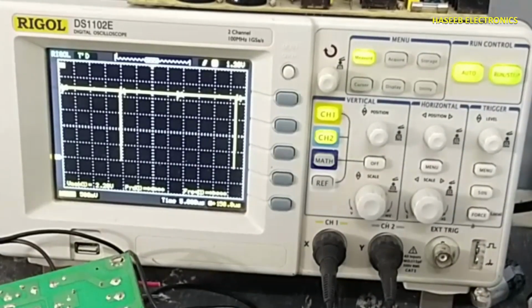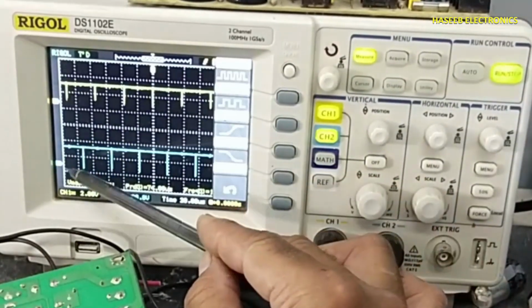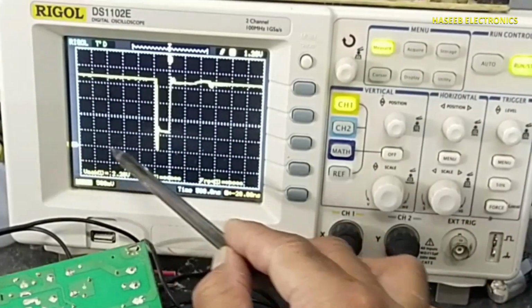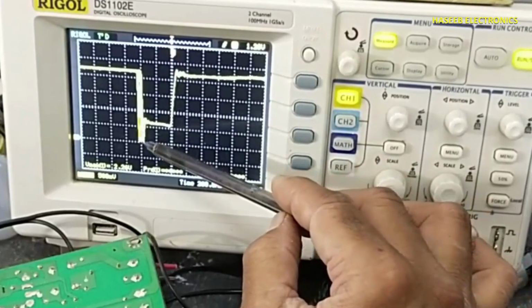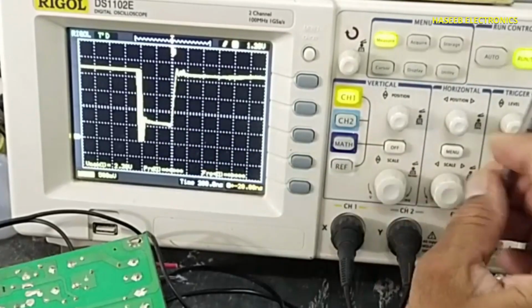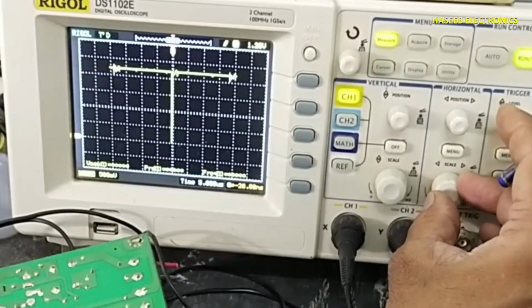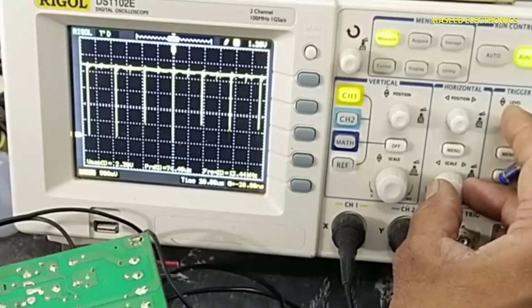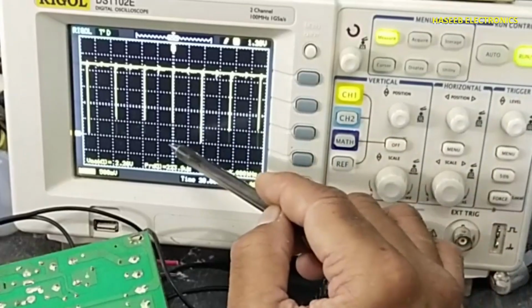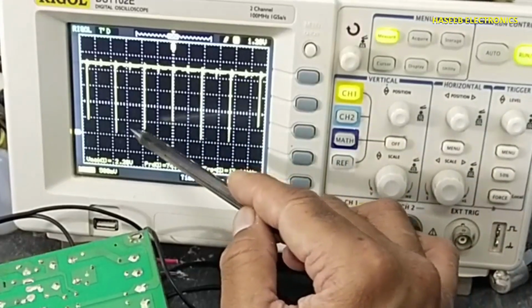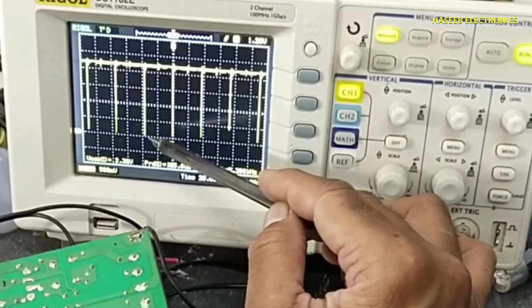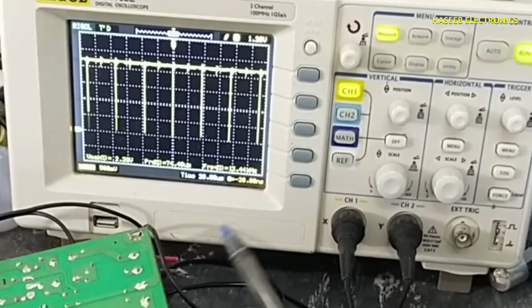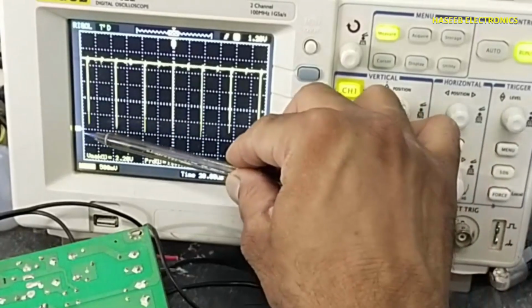Otherwise the signal is starting from the zero line. This is the zero line marker for channel A. Now it is a very clear display of the signal. When we close the screen to display multiple signals, sometimes it will skip those narrow peaks. Otherwise the signal will start from its zero marker line.